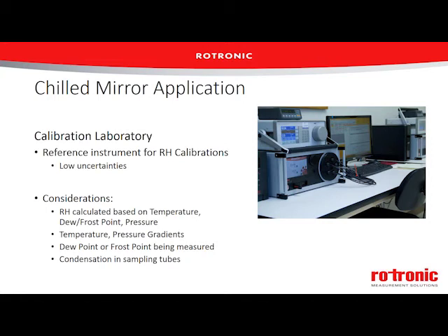We definitely need to consider that any relative humidity value that they report is calculated. That means it's based on the air temperature, and it also needs to have an idea of what the pressure is. Some of these devices will have a pressure sensor on them. Others will make an assumption about what that pressure is. But if that pressure value is incorrect, our relative humidity value will be incorrect as well.